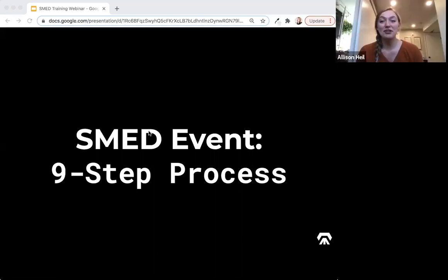Average changeover time definitely depends on your industry. A lot of folks are totally good with 4 hours. I think that's generally a long time, but we can try to get it down. World class is getting it into the single-minute range, so you want to try to get it under 10 minutes as a goal. But depending on the industry, your changeovers definitely vary from 30 minutes to 20 minutes to 4 hours, 8 hours. It just depends on what kind of work you're doing.